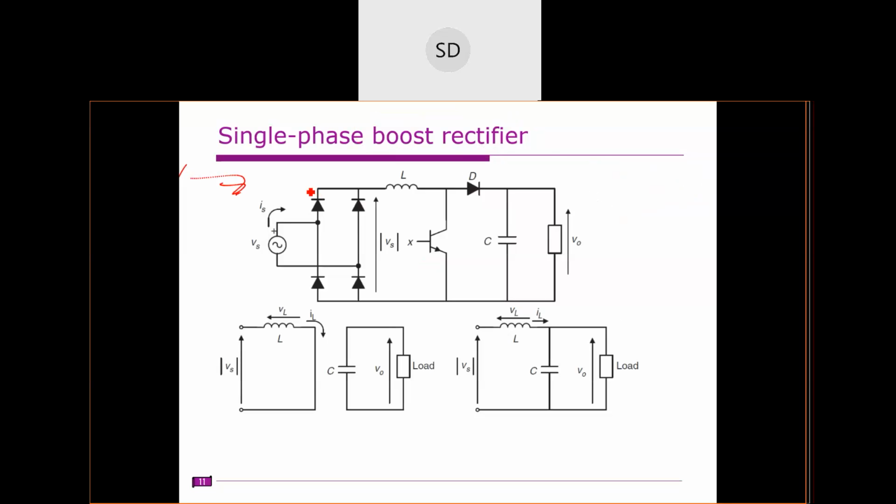Okay, so this is connected to a single phase bridge rectifier. What kind of output voltage can you expect here? This is Vs, so you can expect mod Vs, right? So if this waveform is something like this, that is the rectified output, agree? This is the output voltage across this bridge rectifier. Clear?